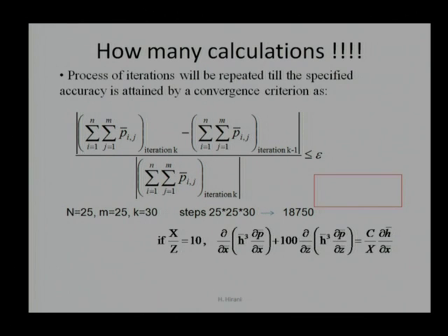Now, if I take this assumption, say the dimension in the x direction is 10 times the dimension in the z direction, what we are going to get is something like 100 versus 1, and this term is neglected. So, I have to consider only the z direction. What is the meaning of that? I do not require any node in the x direction. Pressure terms in the x direction are negligible. Why do we require any node? I do not have to divide that plate.